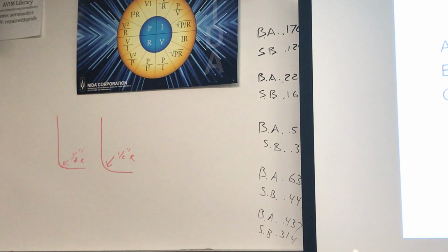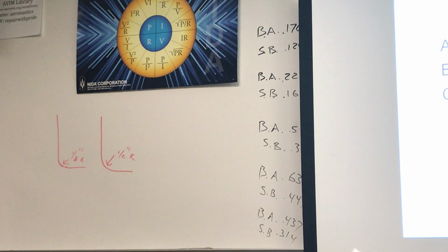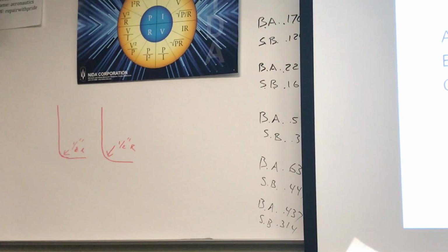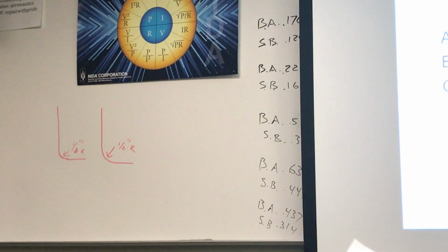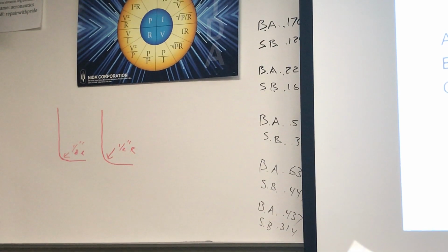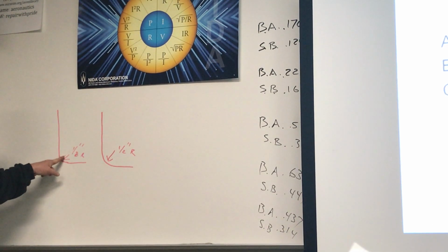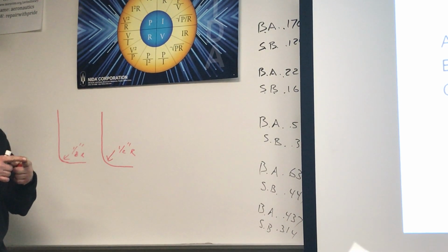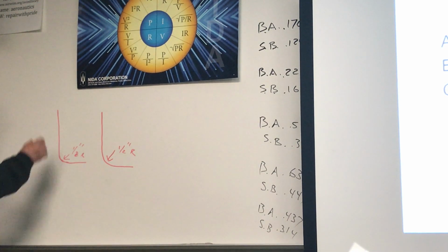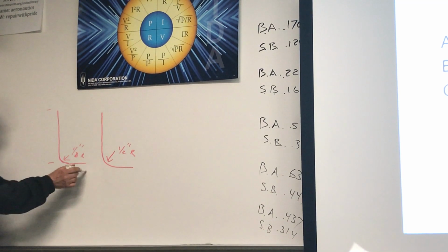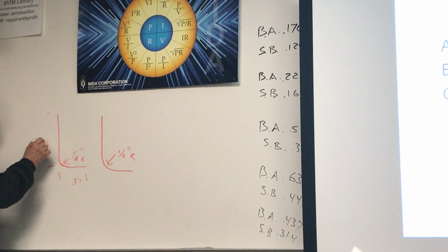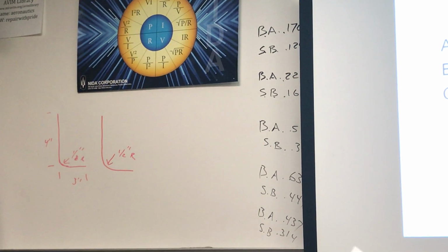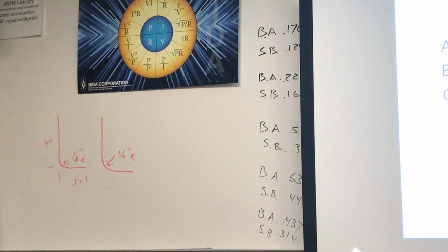Which one of those two parts is going to require the most amount of material? The one with the smaller radius. So this is going to require more material to make. You had to push the material deeper into the corner in order to make that part. So if you're trying to hold dimensions, let's say 4 inches by 3, you had to push it into a deeper pocket, so that means that it's going to require more material to make it, correct?